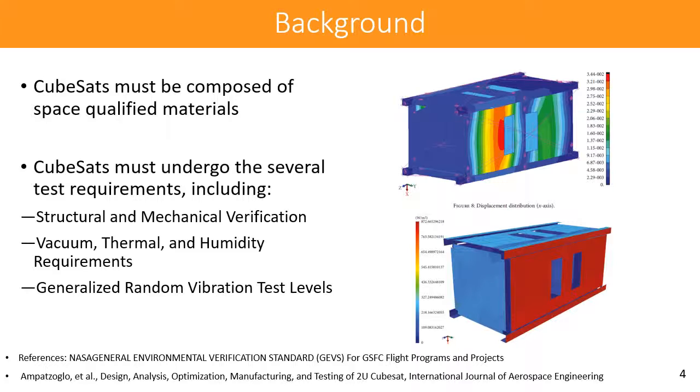CubeSats need to be built of space-qualified materials, and they must also undergo several test requirements. I did not list all of them, but they include structural and mechanical verification, vacuum, thermal, and humidity requirements, and general random vibration testing.